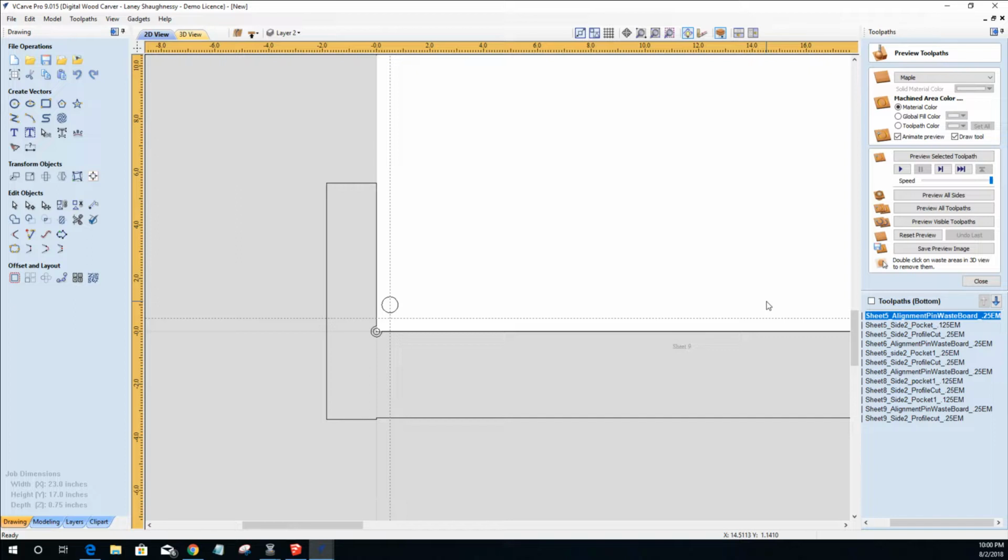Yeah. So you want to cut your panels, and you know it's a 23 by 17 inch panel. Even if you don't cut them on the same day, hopefully your table saw, if you're using your table saw to cut down your sheet goods, is pretty square. Worst comes to worst, you can take an oversized panel, put it on your CNC, and cut out a 23 by 17 inch square out of it, and you know it will be square.